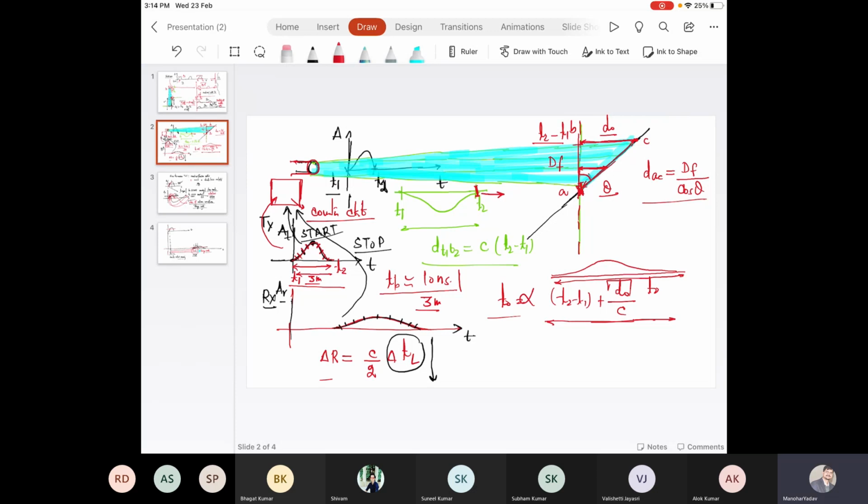And we have also seen that the same process we adopt when the return is received at the receiver end. If this is the shape of the return signal, then at a particular time when it is received by the receiver, that energy level is identified by the receiver. Then a trigger signal is generated for the counter to stop the counting.